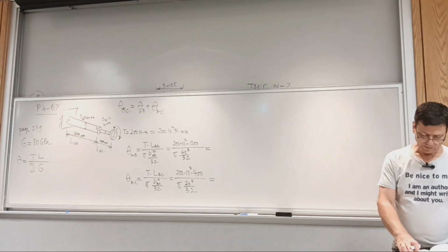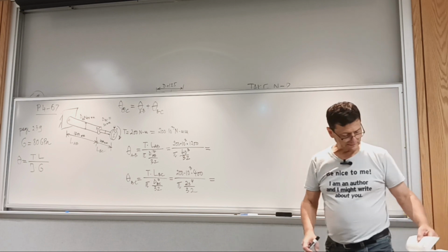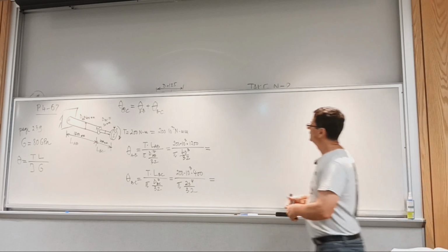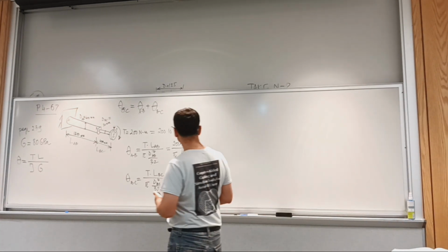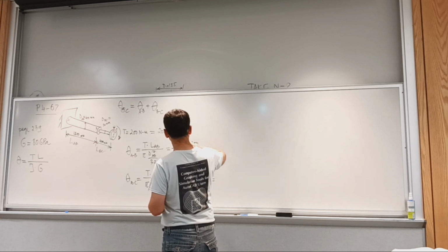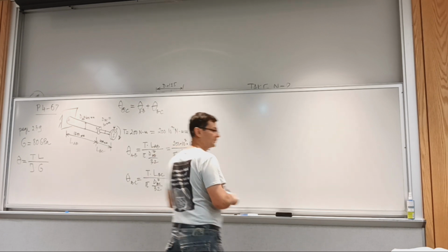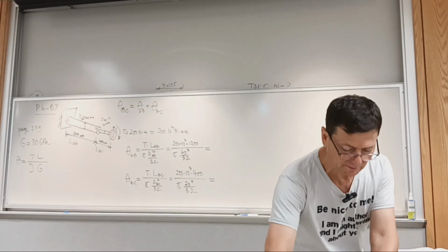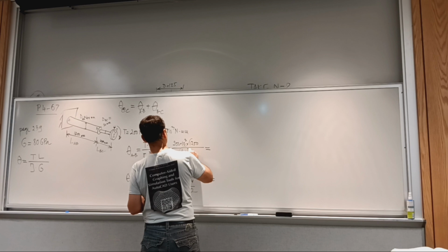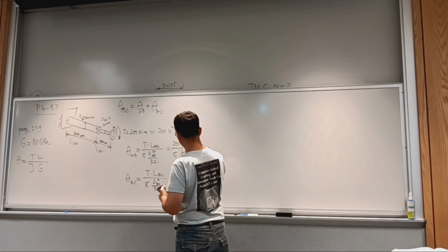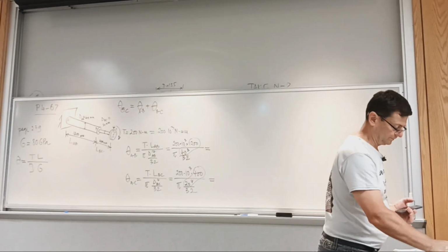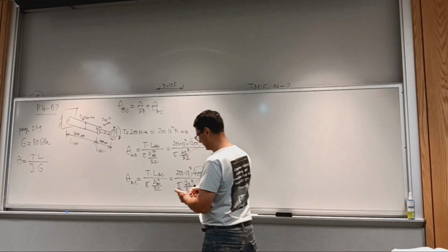So yeah, to confirm, we use the formula pi diameter to the power 4 over 32 on appendix 1, which is page 753. Let's put some numbers on these. We can unify these equations, they differ by this piece, right? In an exam situation, you'd think, how can I save some time? We can calculate the common part and then multiply by what I encircle in blue.